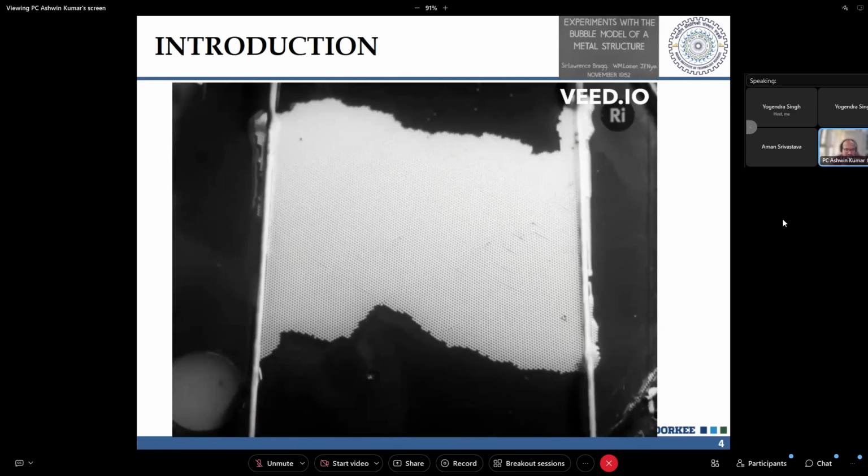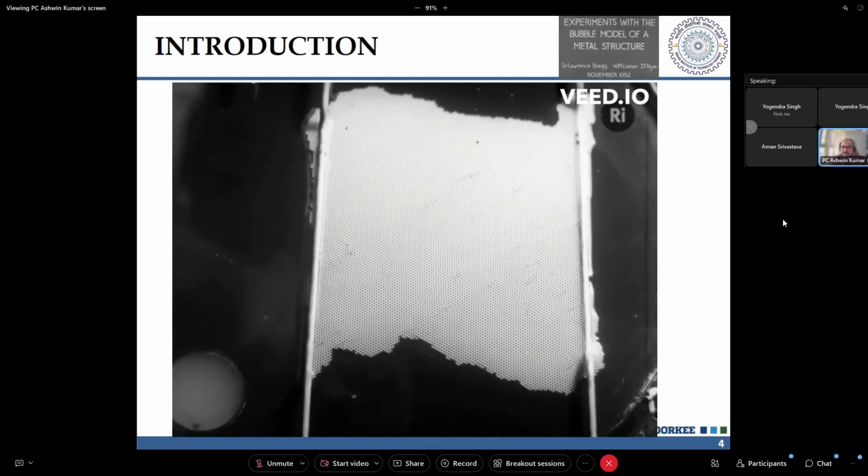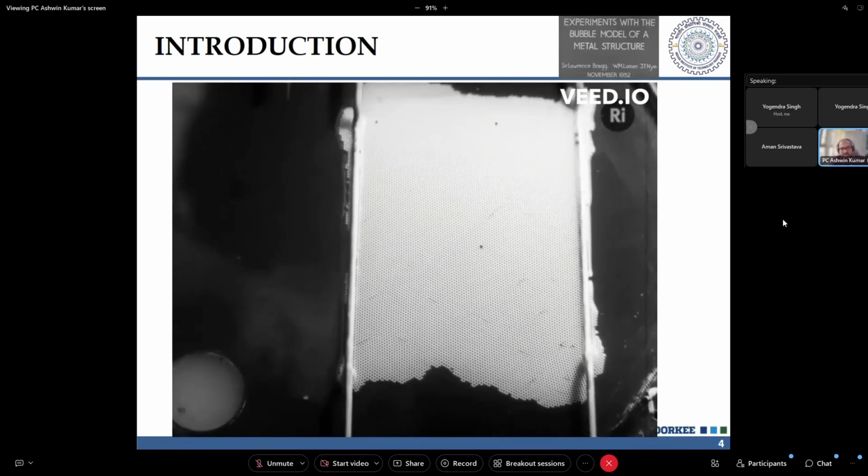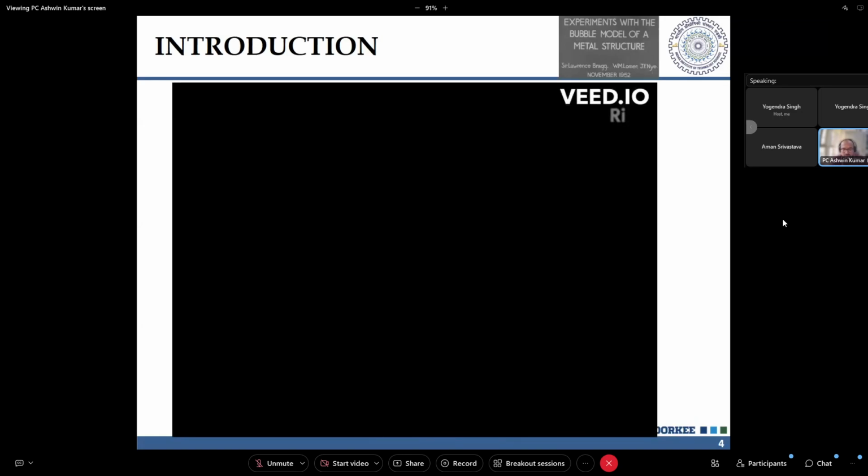If the deformations are small, the metal may come back elastically to rest. So why did I show this video? I recommend everyone watch it. This is just a small bit of the 16-minute video with the bubble model experiment. There you can easily understand what a dislocation means, and what happens when a metal plastically deforms. There is a certain permanent set that is developed in a metal.